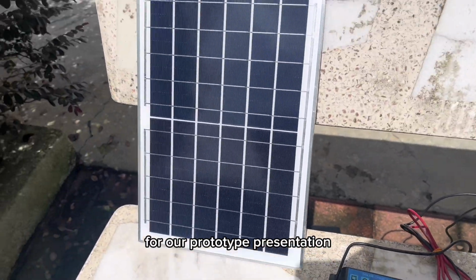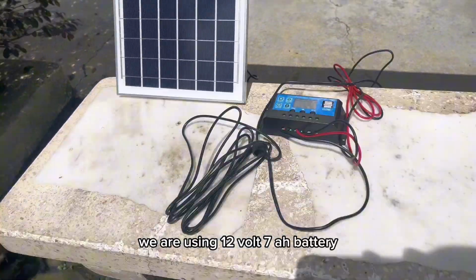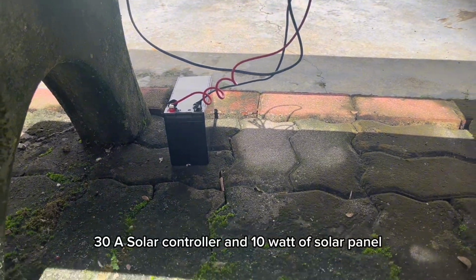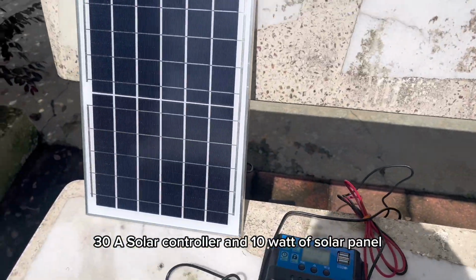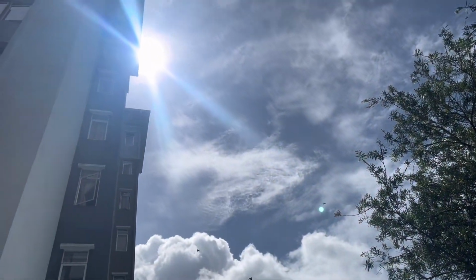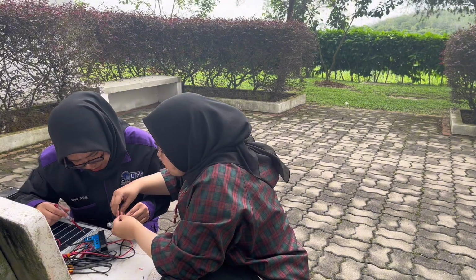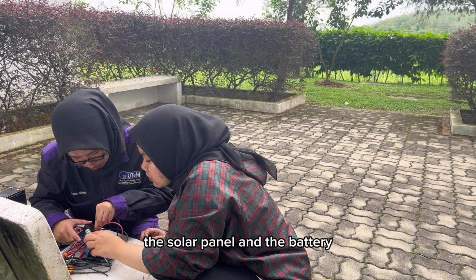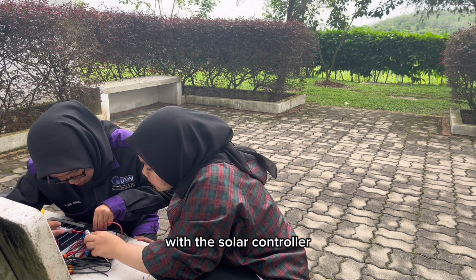So for our prototype presentation, we are using a 12 volt 7Ah battery, 30 amp solar controller and 10 watt solar panel. Firstly, we assemble our equipment by connecting the solar panel and the battery with the solar controller.